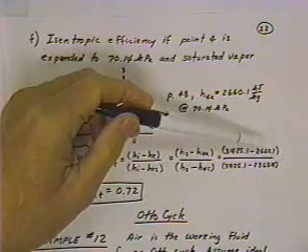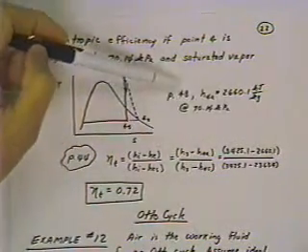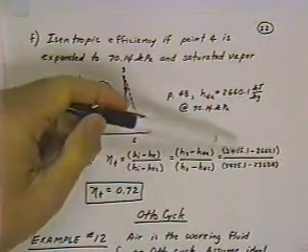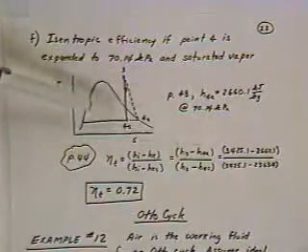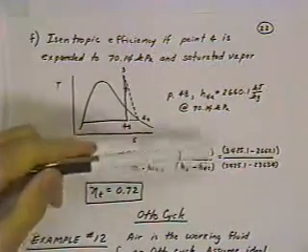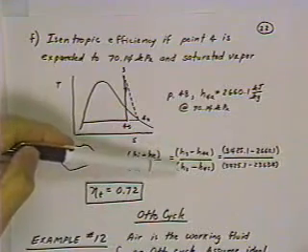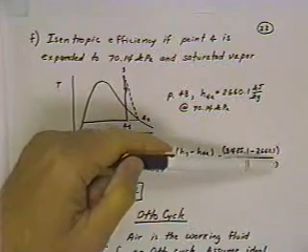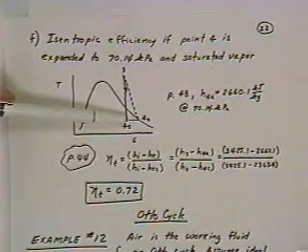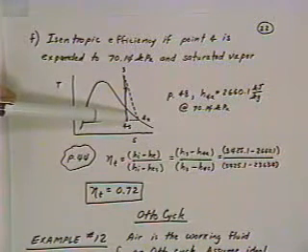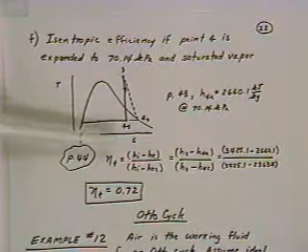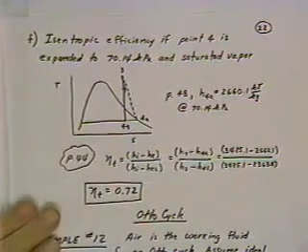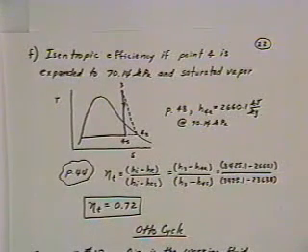And so that turns out to be, if you look back in your table on page 48, 2660.1. H3 is 3425.1, our state entering the turbine, and the theoretical efficiency then, H3 minus H4s, is the 3425 minus the 2363.4 that we calculated as the isentropic expansion through this particular condition. So if we do that, we get an efficiency of 0.72, which gives us the isentropic efficiency for the turbine.